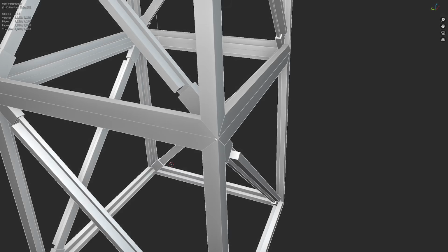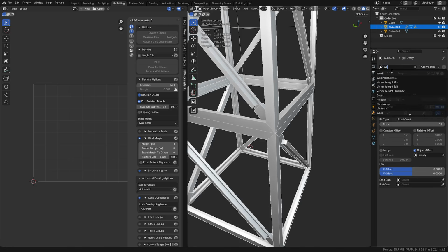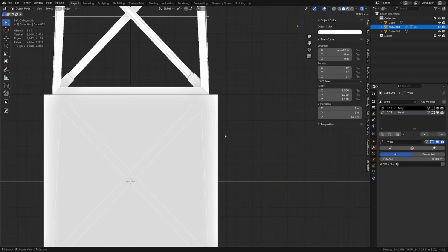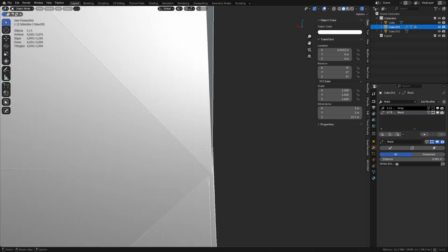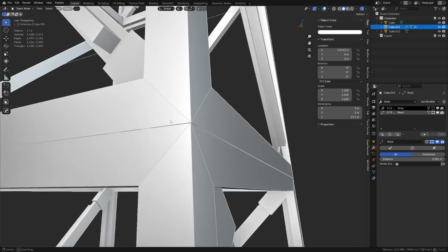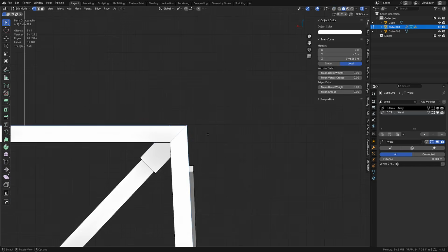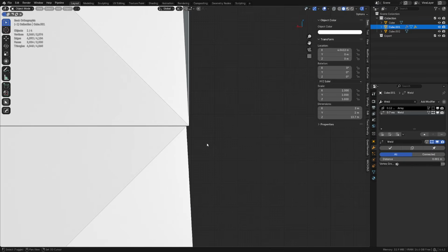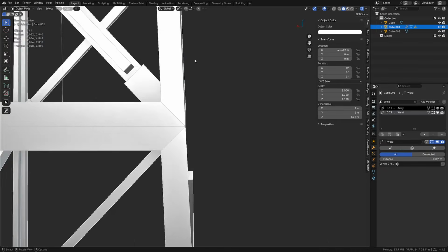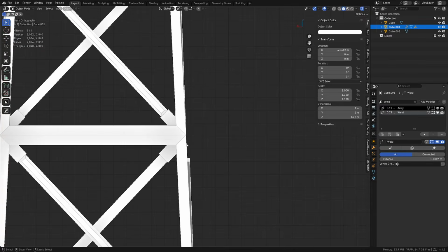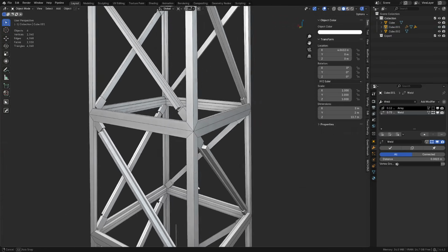Also, these are not joined together. You need a weld modifier, okay? And that would actually go ahead and finish the joining of those pieces potentially. Like we won't really see much of a result here, perhaps. We might not anyways. You can see they're misaligned just a little bit. Okay, so you could take your time to get that more correct, but let me crank the weld modifier up a little bit and they should, yeah, eventually snap together. We just want to make sure that's doing that more than likely all the way up where they're actually going to weld. And you can see we got some other stuff going.